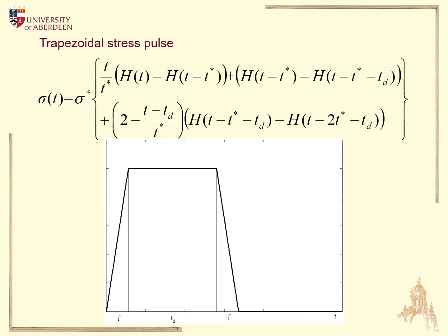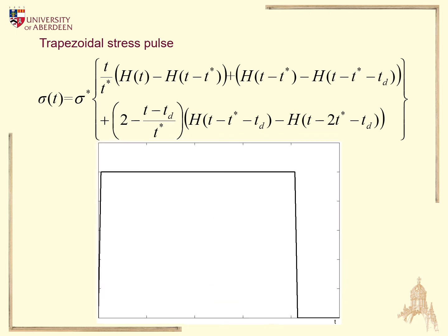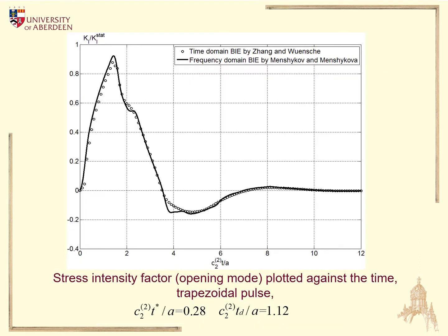And the whole idea is we consider trapezoidal stress pulse, but we make it very steep, like that. In this case, we have a stress pulse which is very close to the Heaviside one. And when we use this pulse, and if we repeat this pulse many times, we may use our previous technique because we may easily approximate the repeating pulse using Fourier coefficients and Fourier series.